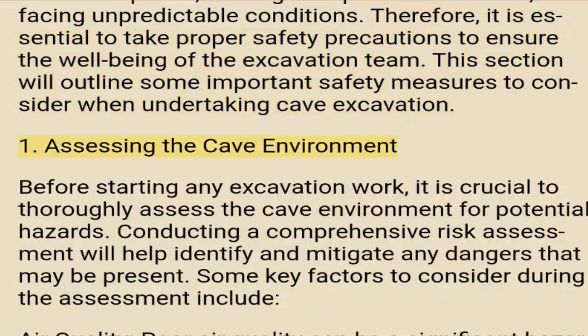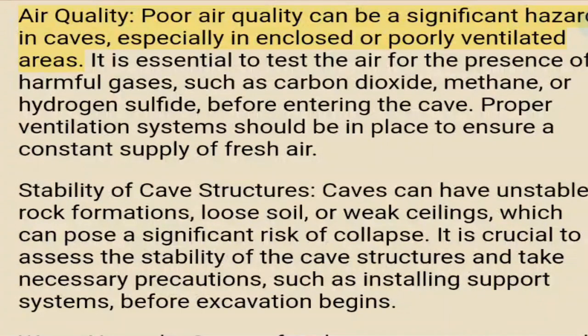1. Assessing the cave environment. Before starting any excavation work, it is crucial to thoroughly assess the cave environment for potential hazards. Conducting a comprehensive risk assessment will help identify and mitigate any dangers that may be present. Some key factors to consider during the assessment include air quality. Poor air quality can be a significant hazard in caves, especially in enclosed or poorly ventilated areas. It is essential to test the air for the presence of harmful gases, such as carbon dioxide, methane, or hydrogen sulfide, before entering the cave. Proper ventilation systems should be in place to ensure a constant supply of fresh air.